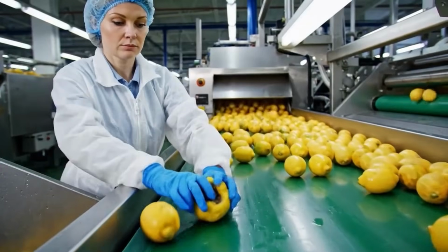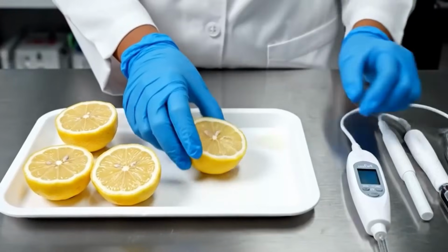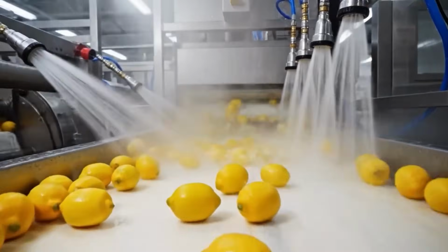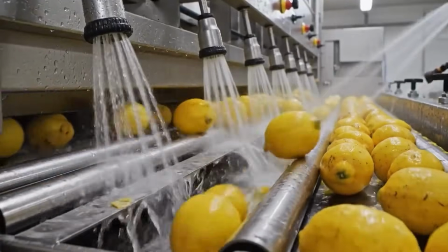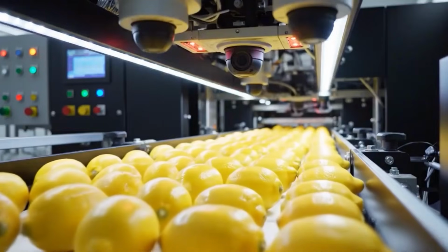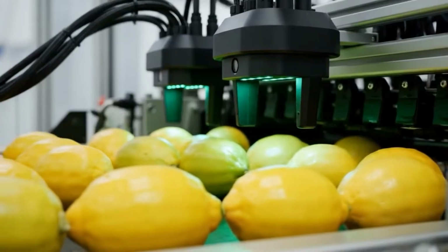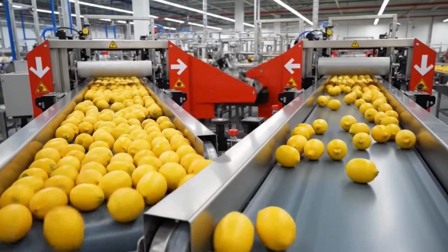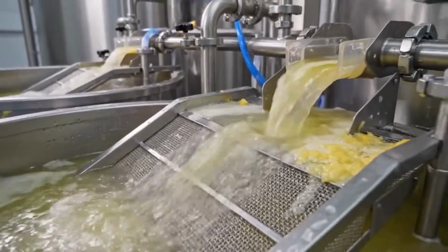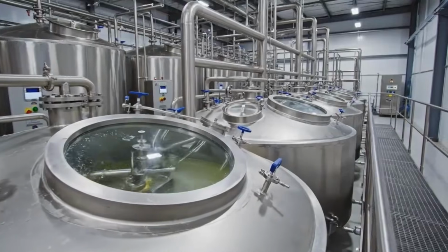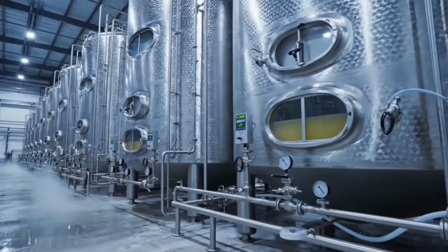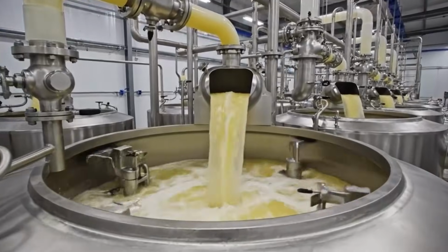Fruit inputs, often high viscosity purees or concentrates, are pumped from cold storage tanks maintained at 4 degrees Celsius. These tanks are fitted with bottom-mounted paddle stirrers to prevent sedimentation of pulp or particulate matter. The fruit component is introduced via jacketed stainless lines with rotary lobe pumps that preserve particulate integrity and ensure steady laminar flow. Inline flow meters measure delivery in real time, adjusting valves based on programmable batch set points.